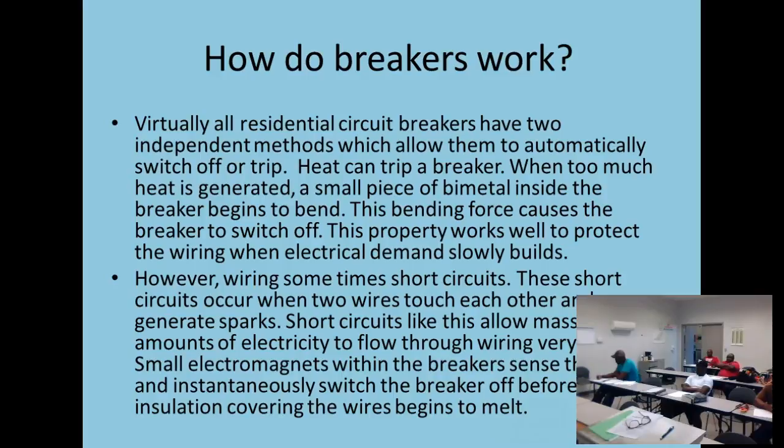Now, the most important thing, though, let's say this is the service entrance panel into your house. But let's say you get down to the disconnect on the outside of the house where the unit is. We still use this direction, right? It went into your breaker. The breaker went through the house, went to your disconnect. Now we're going to classify the disconnect the same way. This is line with L1 and L2.